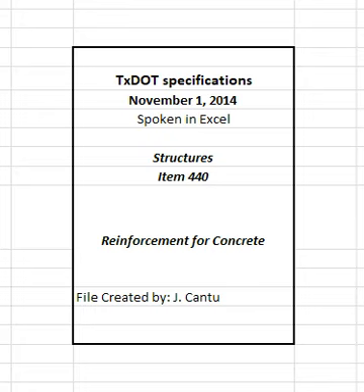3.5 Placing. Place reinforcement as near as possible to the position shown on the plans. Do not vary bars from plan placement by more than 1/12 of the spacing between bars in the plane of the bar parallel to the nearest surface of concrete.